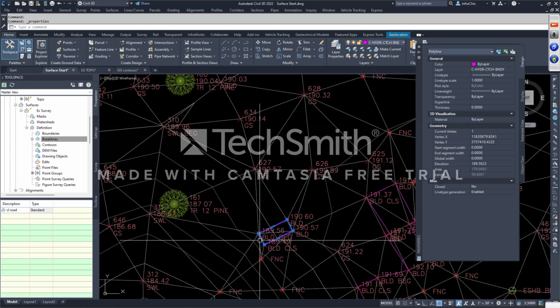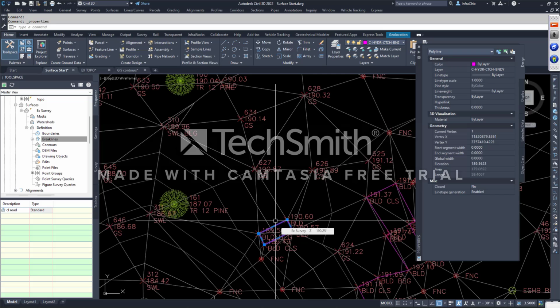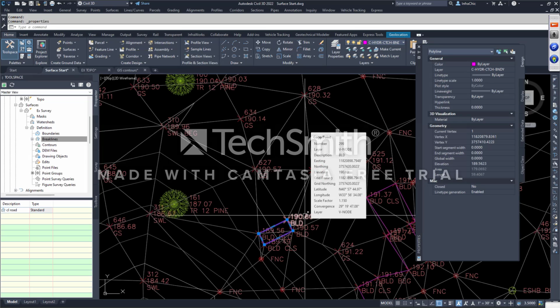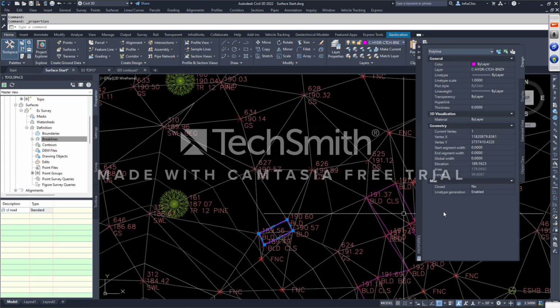The edge of the dirt against a building is always 6 inches lower than the finished floor, right? Minimum. Sometimes 8, sometimes a foot, sometimes 2 feet, depends. So they're grabbing the edge of dirt up against the building. Usually what I would do is I'd find the highest spot, 190.6, and I'd add 6 inches. So if that's the case, that's 191.2, because that's really where it should be. That would be my finished floor.